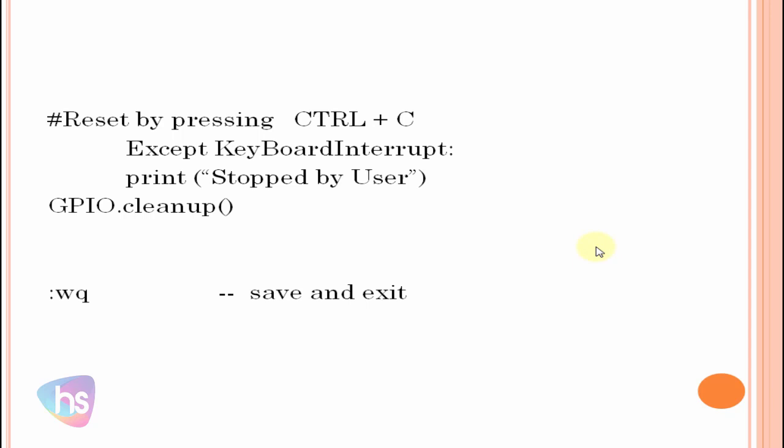And GPIO pins may have already-read data, something that may occur while using electronics. Now we need to clear it with GPIO.cleanup(), the default function. You need to write this line, save and quit from the editor.